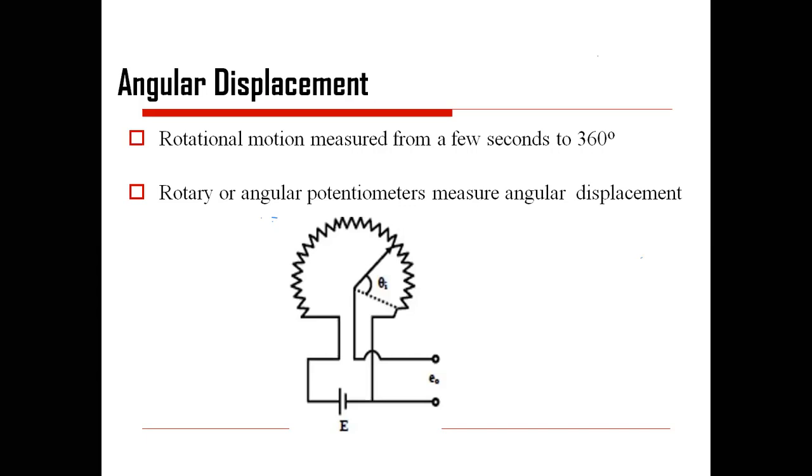However, when you bring the rotation of the pot to one, the resistance included in the path is the maximum. And as per Ohm's law, V is equal to IR, at that time your voltage will be reduced because voltage is directly proportional to R and the resistance in the path is more.